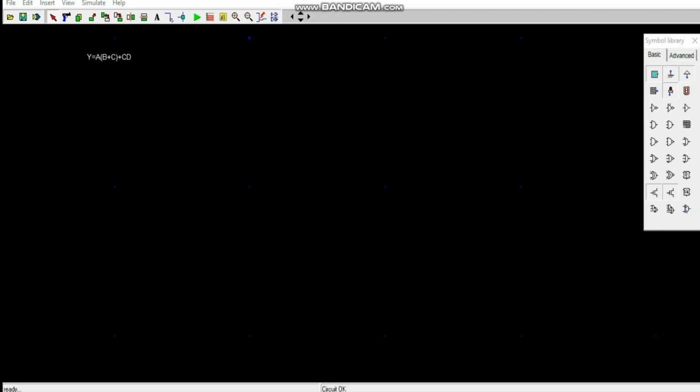Now let's dive into DSCH simulation. To give you a brief overview, right-click for drawing the connections, left-click for component movement, and on the right side you have the library with your components. To remove something, use the gun button in the top left corner, and click what you want to remove.